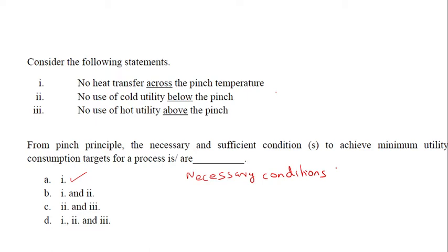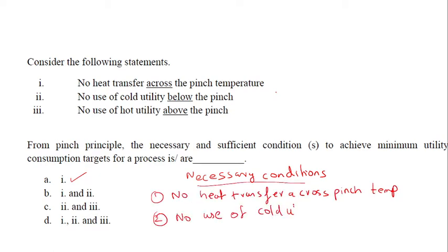Second statement is no use of cold utility above the pinch point. And the third statement is no use of hot utility below the pinch temperature.